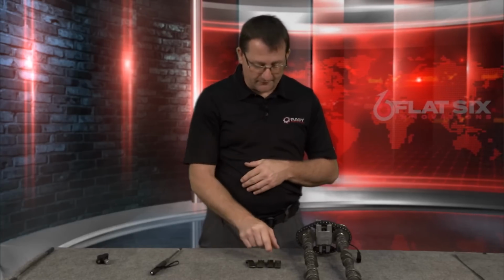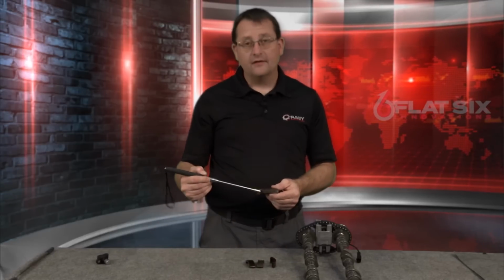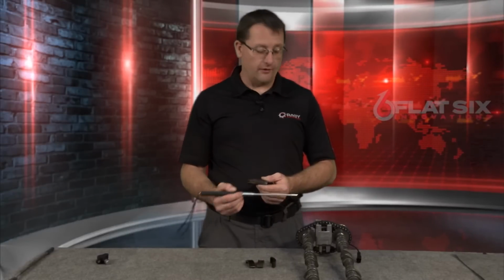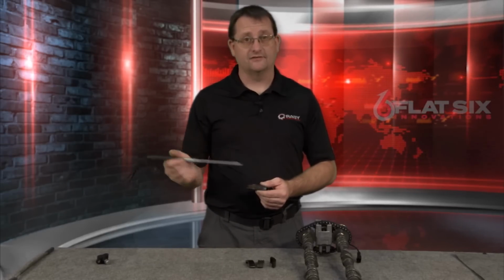Now, some of you are going to watch this video because you found debris in the oil that was the hard brown plastic, or sometimes a little bit dark brown plastic, and you're going to wonder where that came from. Well, that, of course, is known to come from these chain guides, okay, that are located on what I call the 4th and 5th chains, which are a simplex chain that is found connecting the intake and exhaust cams in all the 5-chain engines. And again, that's up to 2001, actually through 2001 in the 996, and up to and through 2002 in the 986, both by base model and S model.